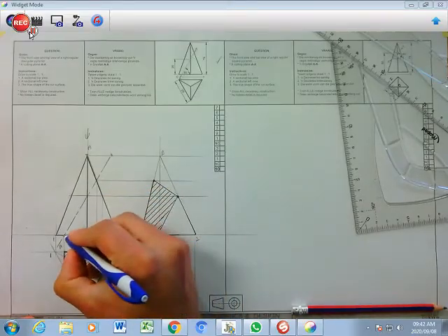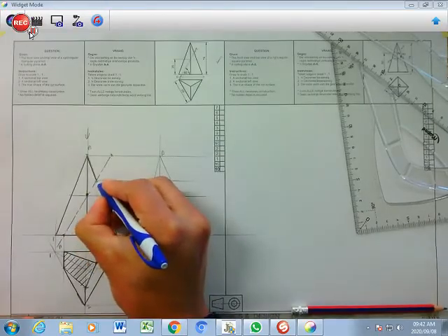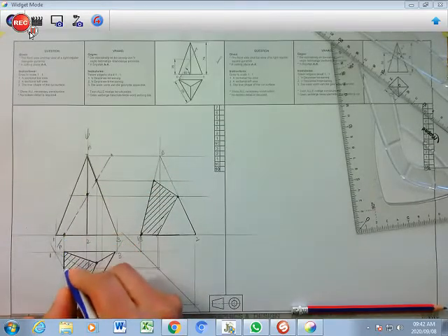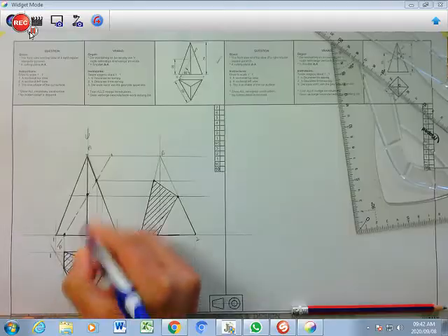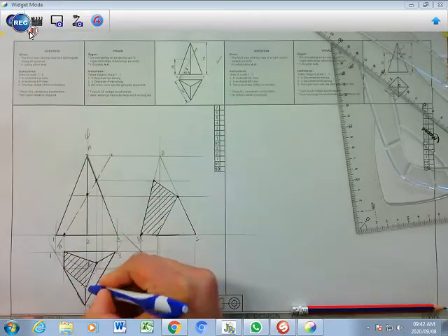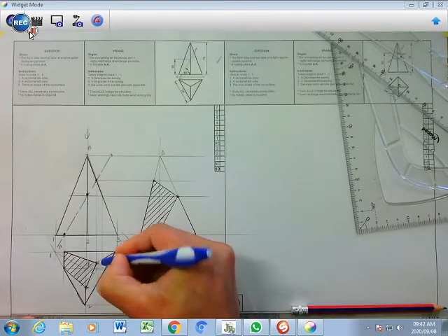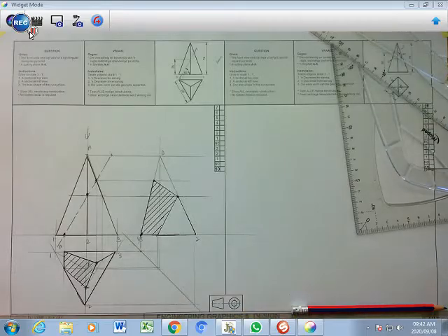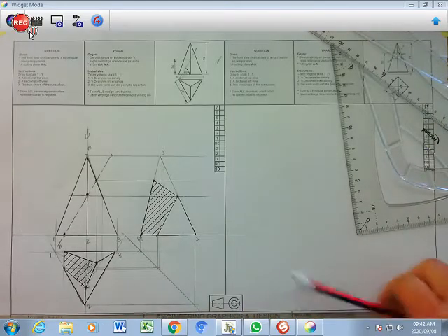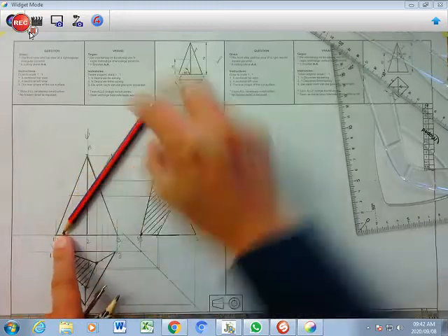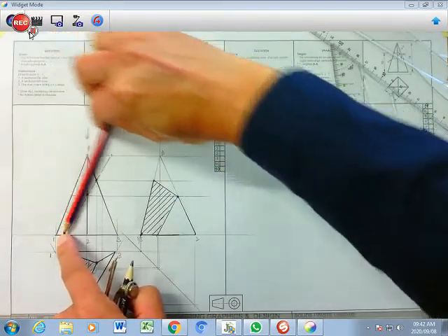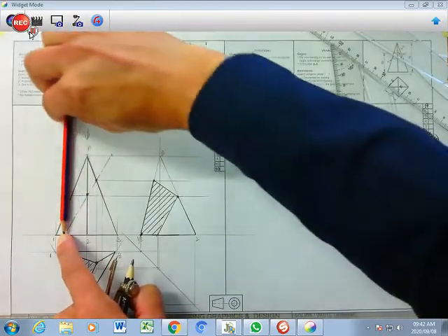Now, these are the 3 cut points. Those are the 3 cut points. That's 2 points. That represents 2 points on the base. That 1 on there. Now I need to draw the true shape only of this section over here. How do you do that? So all I'm going to do is pivot this around this point. I'm going to pivot that, and I'm going to bring that straight like that, because it's a slant. I want to bring it straight.